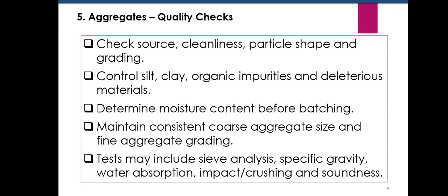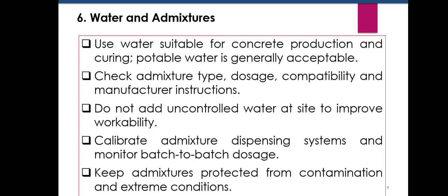Aggregate moisture content is particularly important because surface moisture changes the actual amount of water entering the concrete mix. The grading of fine aggregate and size distribution of coarse aggregate should remain reasonably consistent. Depending on the project requirements, tests can include sieve analysis, specific gravity, water absorption, impact test or crushing test, and soundness.